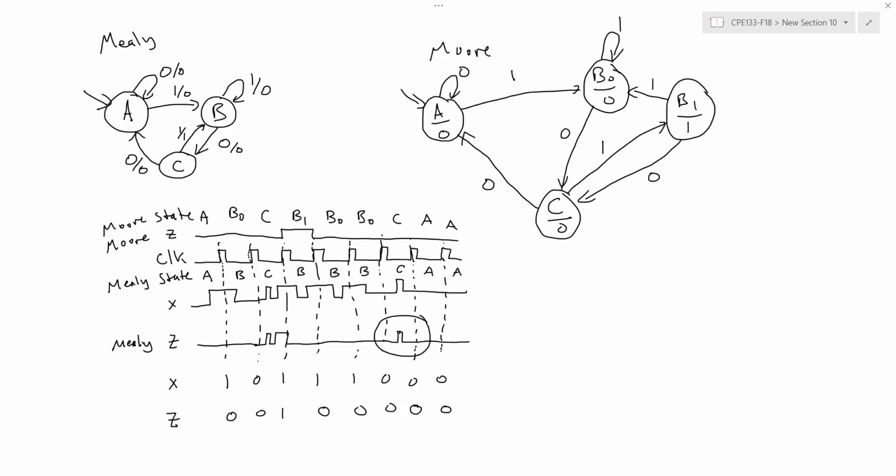The disadvantage of a Moore versus Mealy, as we can tell above, is that I tend to have more states with a Moore style output than using a Mealy style output. But that said, it's typically not many states, and so it really depends on the application and the context which style you use, but both of them can be used for any application.